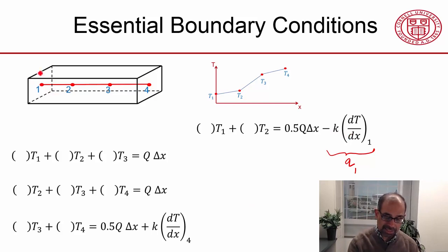On the other hand, at the left boundary, we know the temperature from the temperature boundary condition. So now I bring in the additional equation at node 1 from that temperature boundary condition. The shape that we have assumed has to essentially satisfy that equation. That is, this value of the nodal temperature has to be T0.